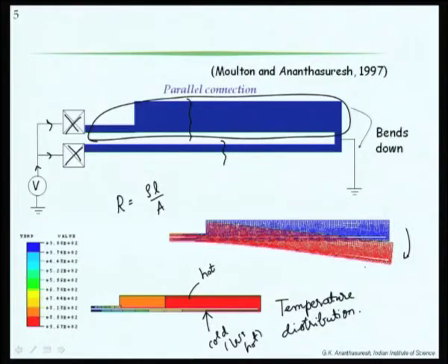What it tells us is that we can take a structure, make holes wherever we want and try to get the type of motion that we want. Again, it is embedded actuation, and making this is rather easy in any microfabrication process that has a releasable structural layer, meaning that there should be one planar layer that is free to move in the plane.